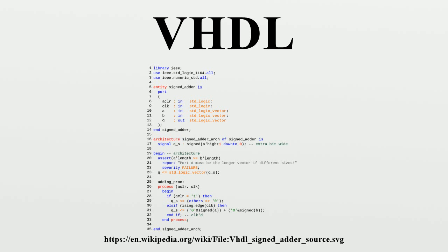Synthesizable constructs and VHDL templates. VHDL is frequently used for two different goals: simulation of electronic designs and synthesis of such designs. Synthesis is a process where VHDL is compiled and mapped into an implementation technology such as an FPGA or an ASIC. Many FPGA vendors have free tools to synthesize VHDL for use with their chips, whereas ASIC tools are often very expensive. Not all constructs in VHDL are suitable for synthesis.